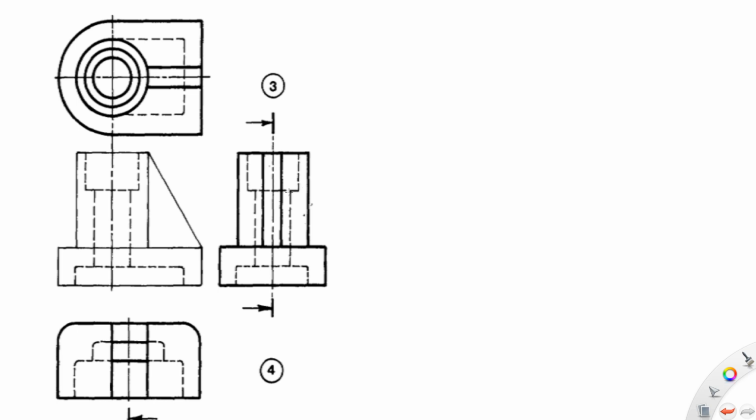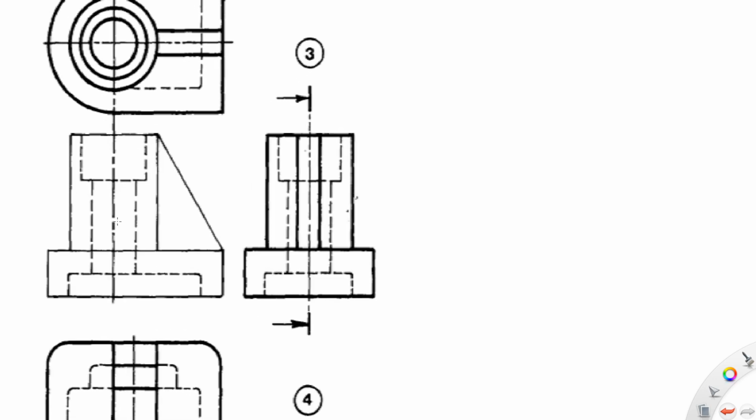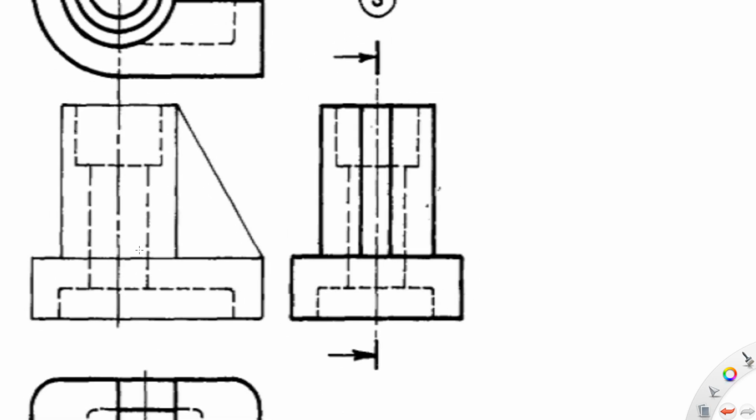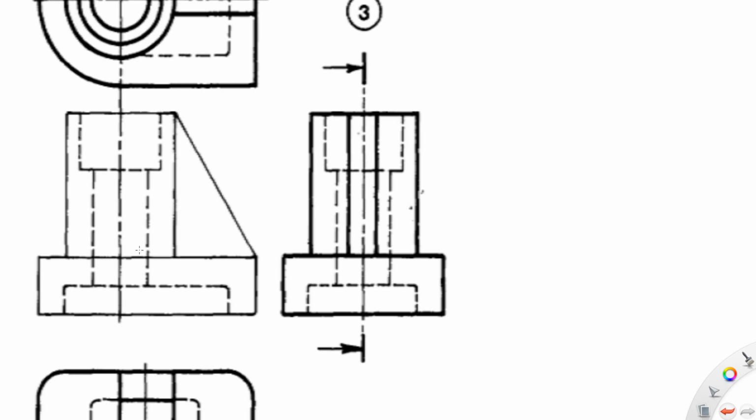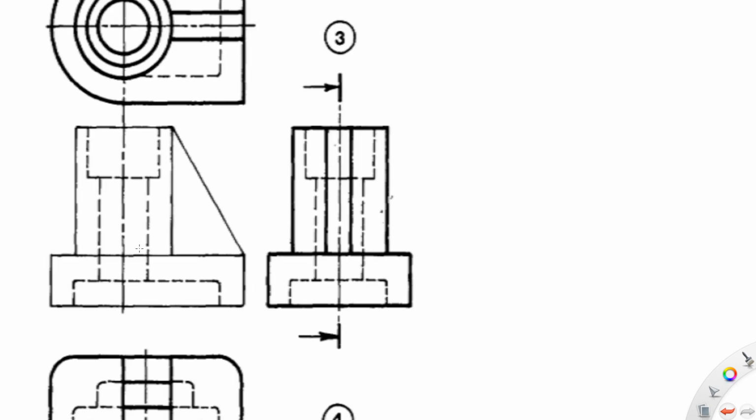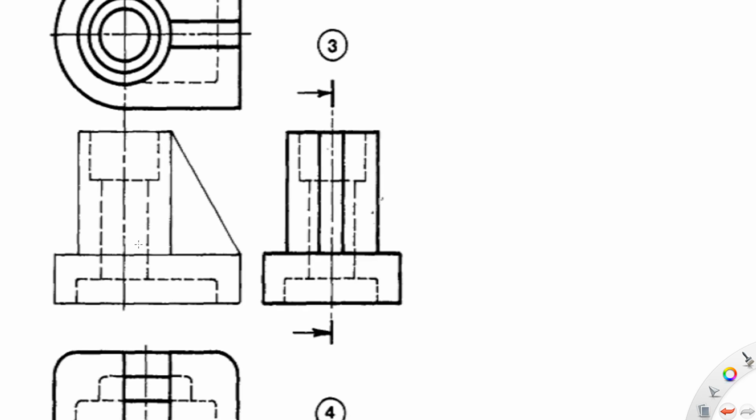In this case, we have the cutting plane on the end view. And that's the direction, third angle projection. So which view are we going to have? That would be the sectional front view. Basically we are going to draw the front view, then we hatch it, we section it. So we provide a sectional front view for this one. To do that we have to sketch.